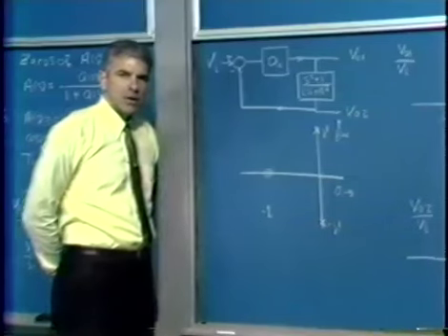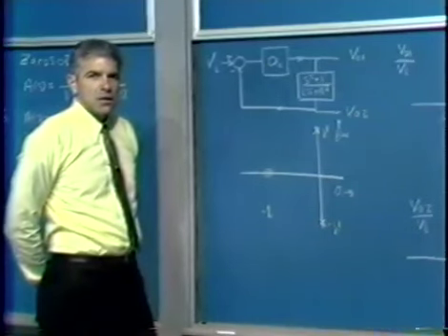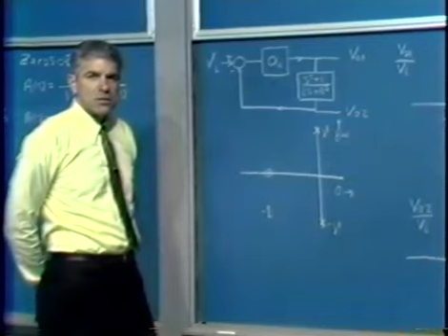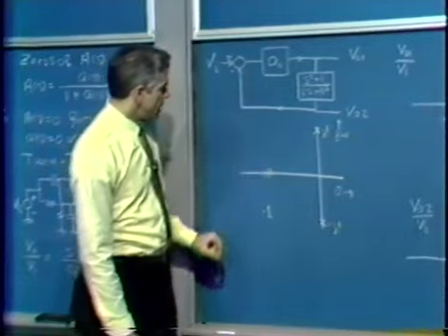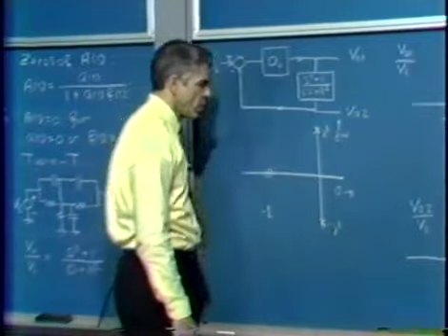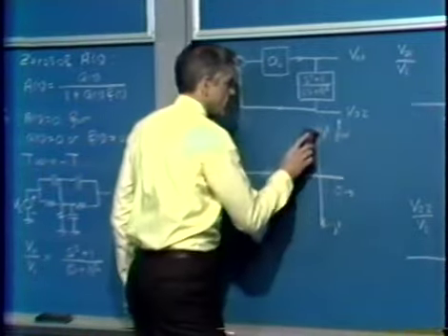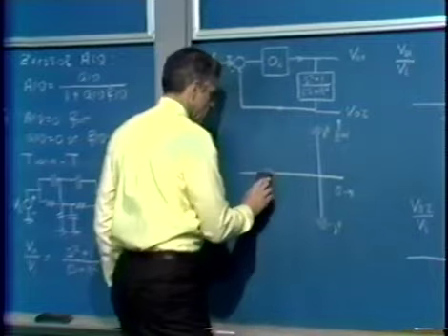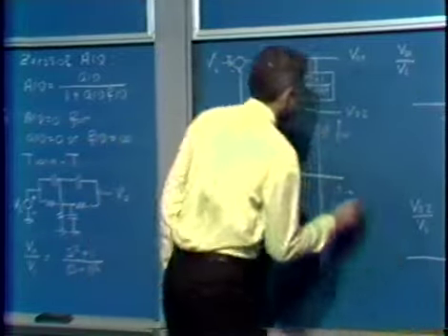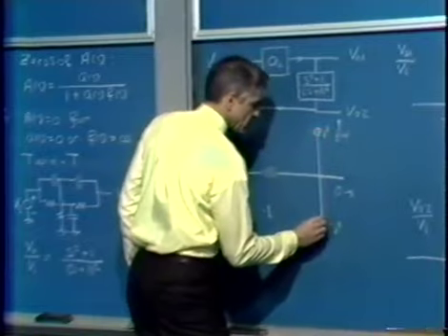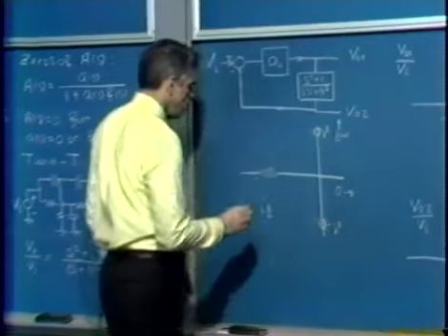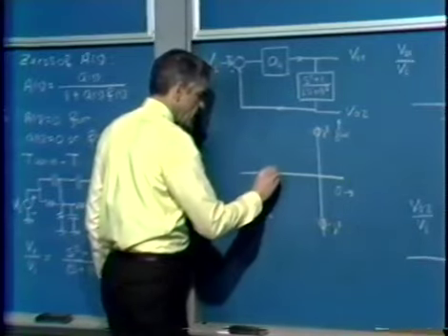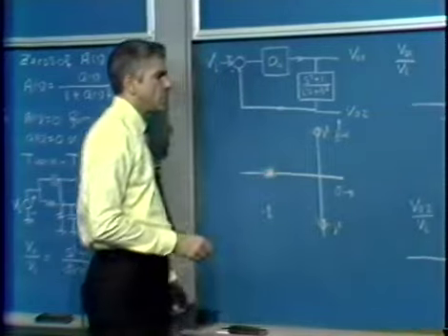And we can do that by our usual root locus techniques. The loop transmission has 2 zeros on the imaginary axis, a complex conjugate pair of zeros, of course. And so we start out with, I'm sorry, I have an error in this one. Let me indicate the zeros and poles correctly. We start out with two zeros in the loop transmission at s equals j plus and minus 1, and we have two poles in the loop transmission at s equals minus 1.